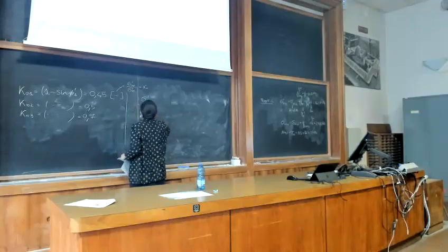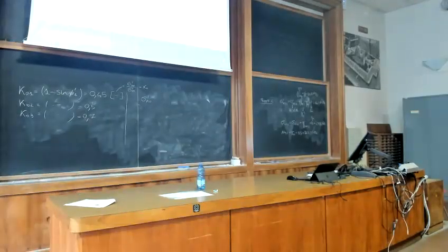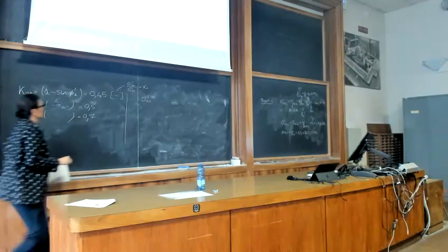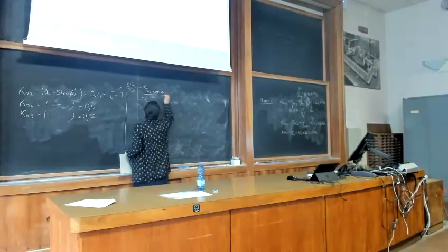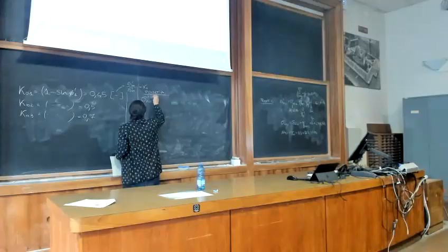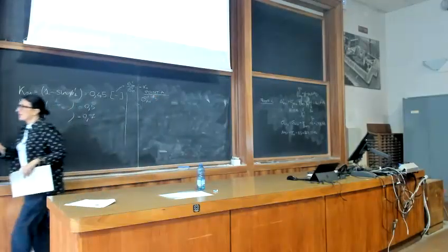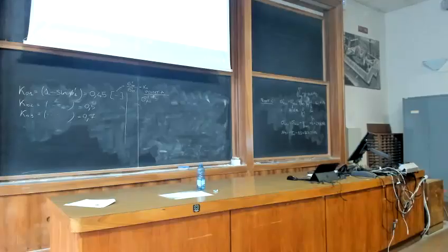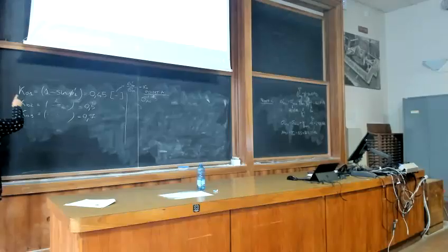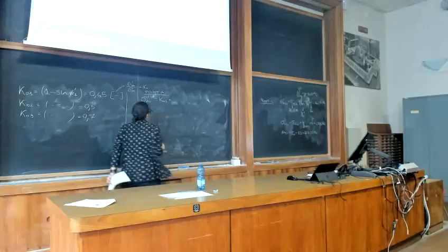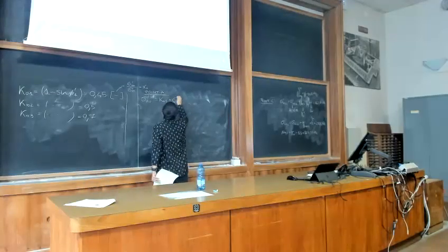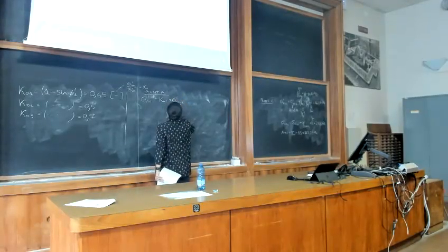Sigma dash H naught in point A, so here we are 3 meters deep in our deposit. So again, point A. First of all, we calculate the horizontal stress state just above the discontinuity when we are in gravel. And so we use K01, and you can multiply that for sigma dash V naught already calculated in point A.